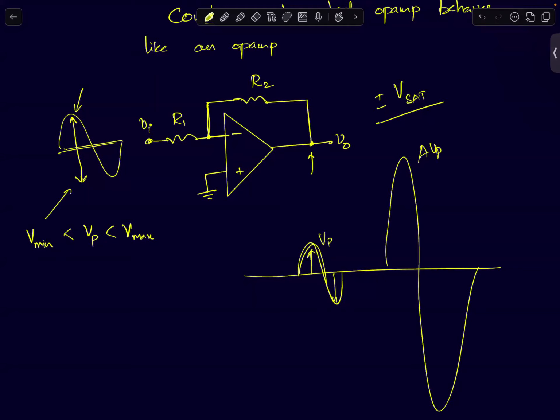An op-amp can be seen as a linear amplifier if the frequencies of the output are the same as the frequencies in the input. There cannot be any different frequencies. If the op-amp is nonlinear, then you will see some different frequencies as well. But for linear amplification, this condition has to be met. The frequency of the output has to be the same as the frequency of the input. Okay, that is step one.